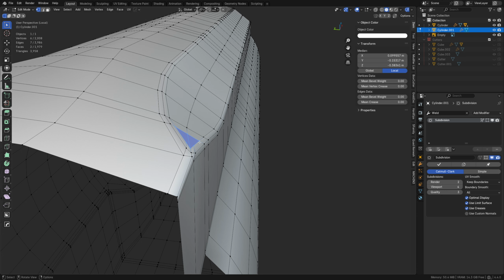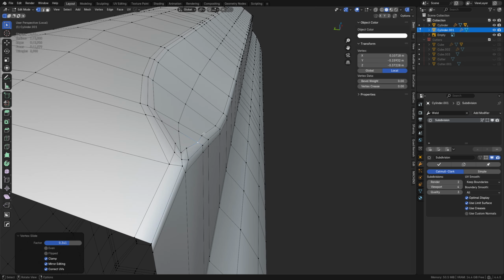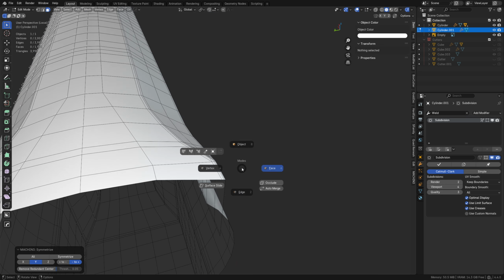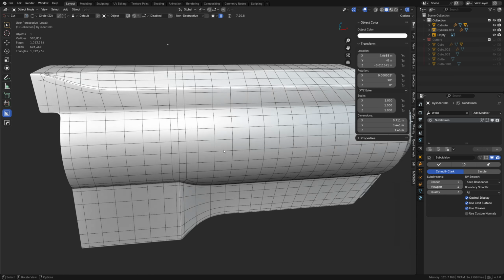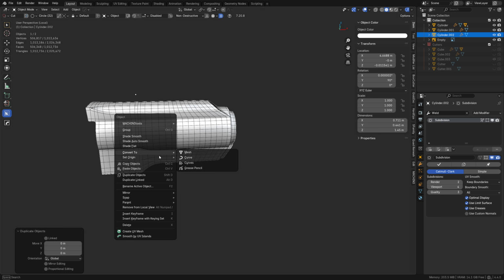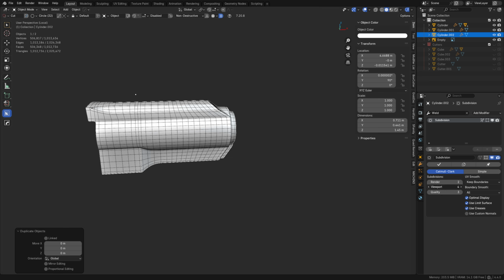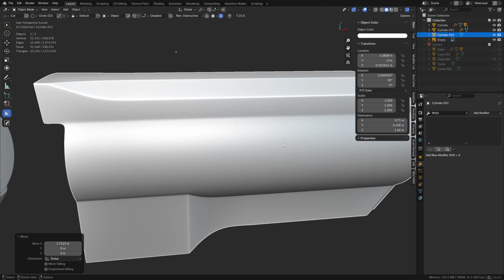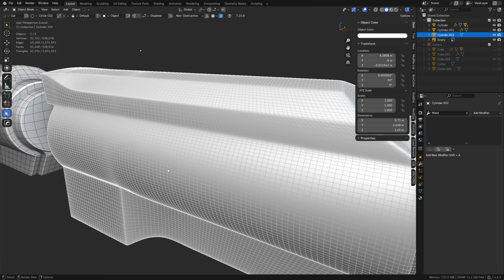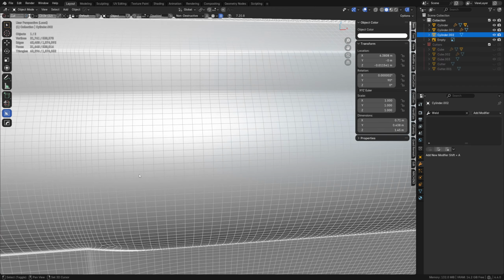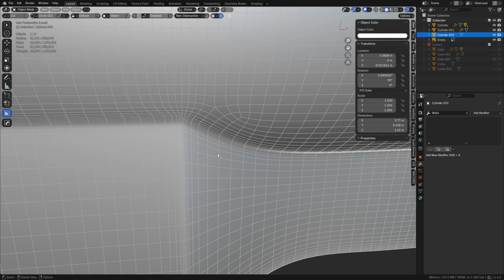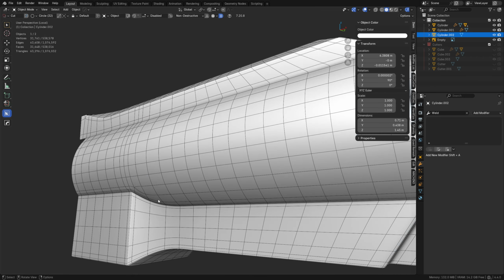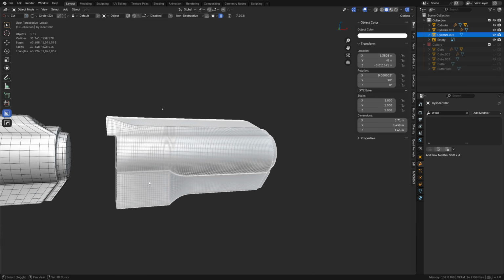But the whole of the model now at this point, it's just tweaking for the most part and adding more details as needed. Because you can take a model like this, and then later on you add a subdivision or two to it, especially if you're doing these for bakes, right? You can work on something like this as well. You can even sculpt on these things if you wanted to. This is why you want to make squares instead of rectangles. If you're planning on sculpting, doing these holding edges is actually kind of a bad thing. You might be better off just adding more loop cuts everywhere than trying to do anything special with them.